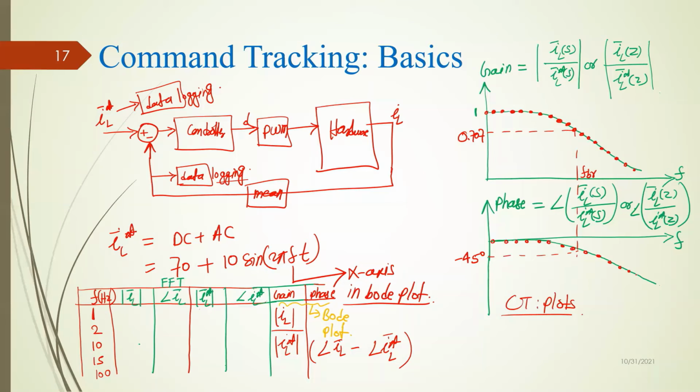Okay, so this is how I have obtained the Bode plot, but there are many tools which you can use to get the Bode plot. But I like doing it this way because in this way you can test your system at a particular frequency also, and it works all the time. There are some tools which work for just one case and do not work for all cases. So I prefer doing it like this, and the method I call the single sine test.